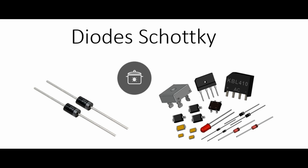Upconversion and downconversion. In wireless transmitters and receivers, mixers are used to upconvert baseband signals to RF frequencies for transmission and downconvert received RF signals to baseband frequencies for demodulation. Frequency generation. Mixers are used to generate new frequencies by mixing an input signal with a local oscillator, LO, signal. Phase lock loops. PLLs. Mixers are employed in PLL circuits to compare the phase and frequency of a reference signal with a feedback signal, allowing precise frequency synthesis and clock synchronization. Heterodyne receivers.